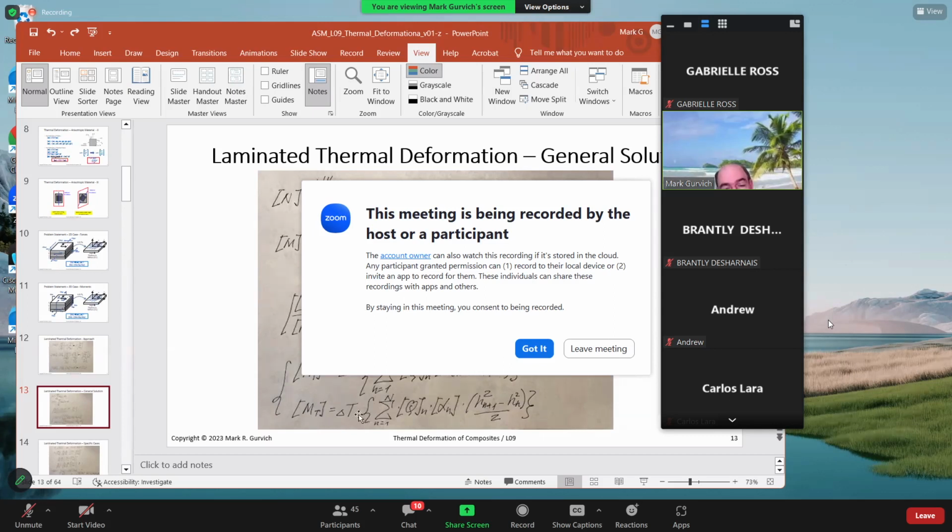And for moments, again a similar format: delta T multiplied by the summation over all layers of the stiffness matrix, multiplied by the CTE matrix, and multiplied, now instead of thickness, by the position squared difference, z squared over 2. Why do we have this? Because it's the integral of z dz, and the integral of z dz is equal to z squared over 2, as we know from calculus. So again, exactly the same approach for analysis, we are just receiving two extra components.